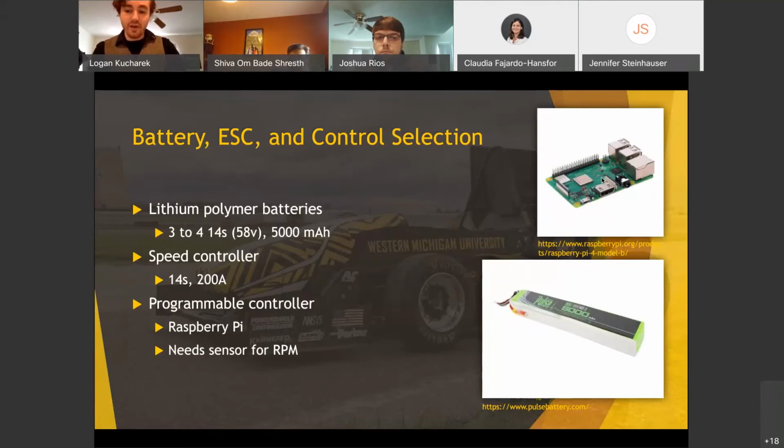As previously discussed, tunability and usability are also critical design metrics of the operation of this compressor. A Raspberry Pi would allow such controls to be implemented, as it can process an incoming signal from the engine RPM and then appropriately configure an output to the compressor motor. While the program necessary to run it will take many iterations to properly configure and test, it's certainly going to produce worthwhile results.